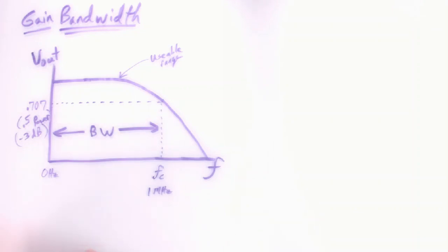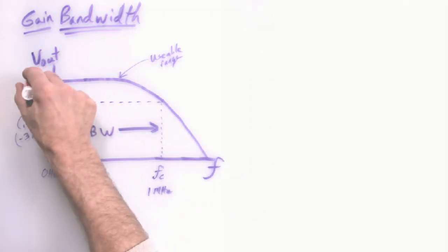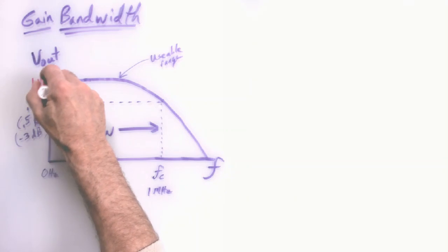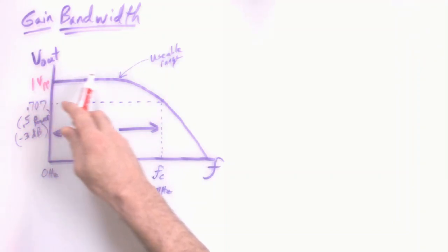Probably another good idea when you're doing a bandwidth measurement, you probably want to use peak to peak measurement in case there is any offset in the signal. That would maybe throw things off. So, if we keep the peak voltage low to a half a volt, maybe, well, that's nice. It keeps our numbers real easy, doesn't it? We could do 1 volt peak to peak as our output, and when the output's doing fine for the op amp.